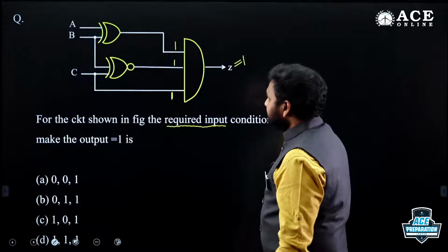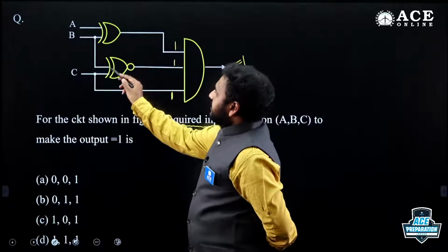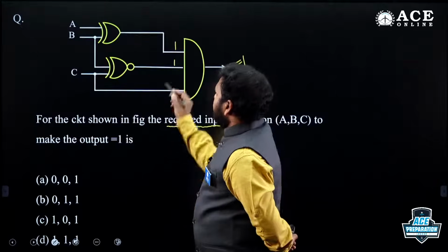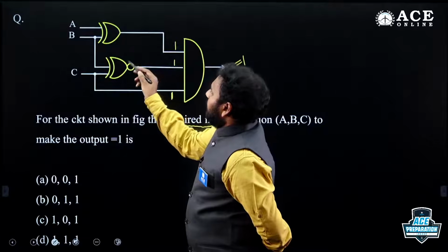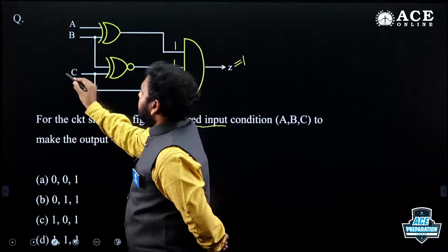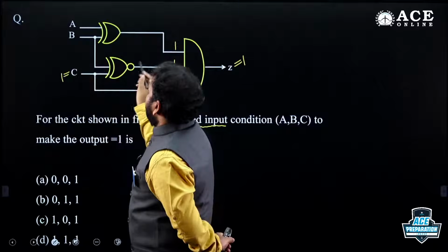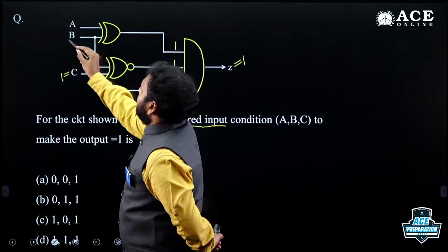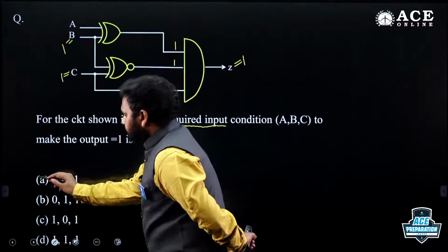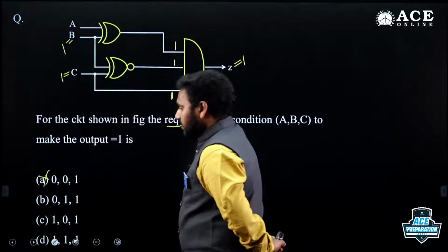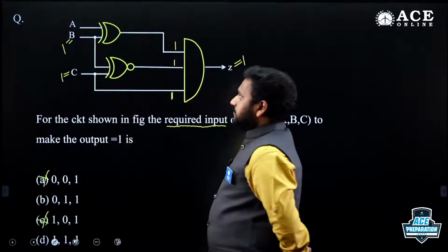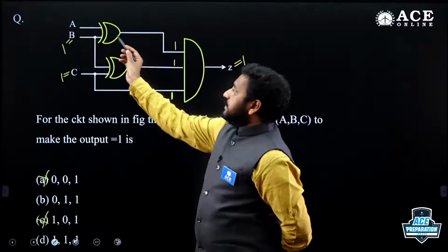Next. What is the name of this gate? Xnor, it is coincident gate. To get 1 here, what should be the next input? Already C must be 1, you know well. To get 1 here, compulsory B also should be 1. That's all. If B is 0, remove that option. For 2 options, B value is 1. And this is not a coincident gate, right?